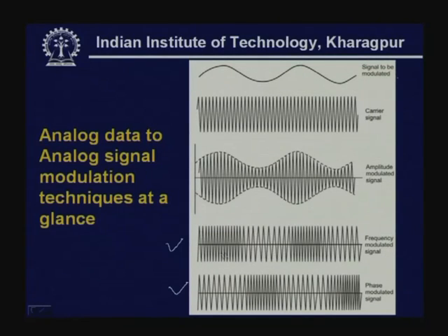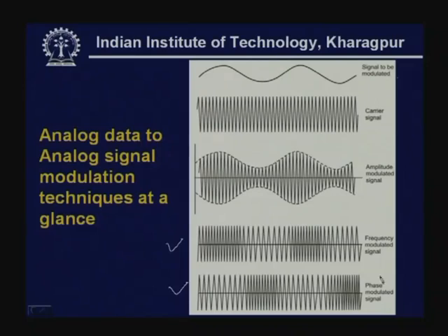Of course, there are some differences in phase between these two signals, but they appear to be identical and their characteristics are the same. So, the characteristics of phase modulated and frequency modulated signals are identical. That means, the bandwidth requirement and power requirement for transmission are the same for both frequency modulated and phase modulated signals. That is why together they are referred to as angle modulation.